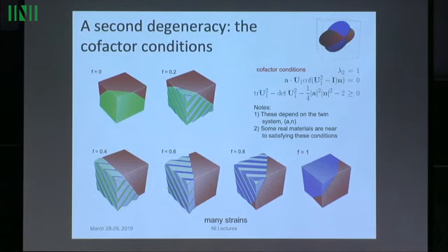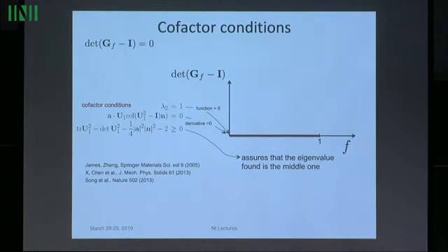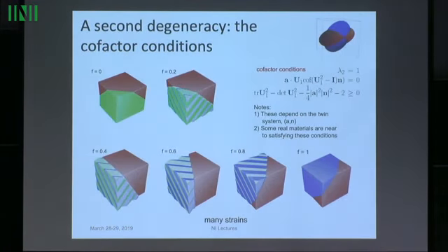So we have the volume fraction 0, you get the single variant. That's because of the endpoint. Of course, the other endpoint gives this one. But then you can continuously vary the volume fraction. And perhaps I overdid it, I exaggerated. This is not a realistic material. I exaggerated the transformation strain so you could really see. But there is a vanishingly small transition layer in there. I think I used linear interpolation for the transition layer, so you can see.